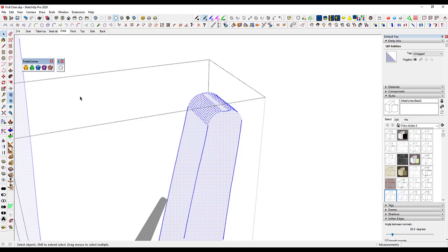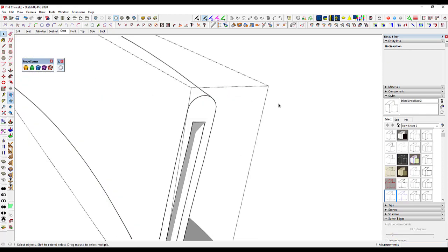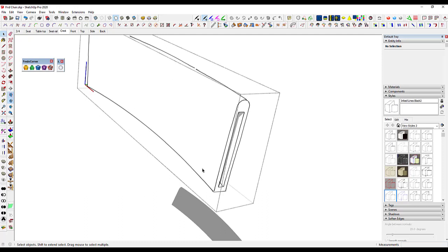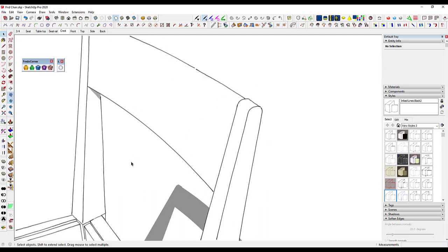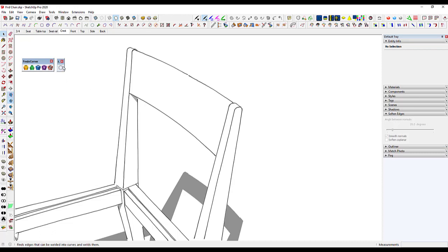So if I select all of this and choose auto weld, let's see, I get my nice curves going around, and do the same thing here. And those curves weren't so short, but now those show as continuous lines instead of little short line segments. So if you use sketchy styles in your modeling, this is nice to have. It's not a free one, but the time it can save you screwing around with trying to get things put back together or fixing exploded curves easily pays for that.